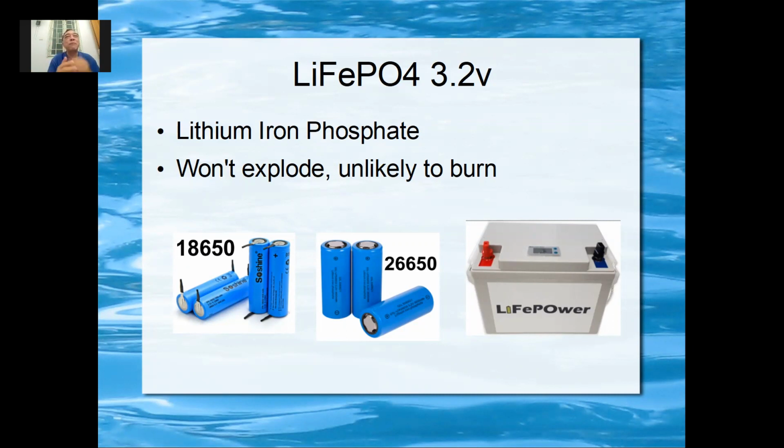Some put 15, some put 16, and then you have a problem already. So when you want to buy a 48 volt battery, you must make sure you know what is the voltage or how many cells are inside there, whether 15 or 16. Normally they are 16, but some will put 15 to make it compatible with the lead acid battery and the gel battery.